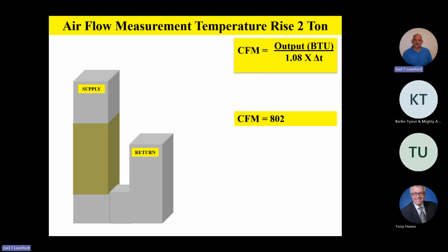Let's do one more just to make sure we've got this. So let's say it's a 4-ton unit. So we're looking for 1,600 CFM on a 4-ton unit. As we take a look at it, we energize the unit. We got the heat strip cooking, and we've got it on the selected speed tap we're testing. And we take the actual voltage at the disconnect of the indoor unit with it running on the heat strips at the desired speed tap, and we have 241 volts. And we take our amp probe and we measure 50.1.